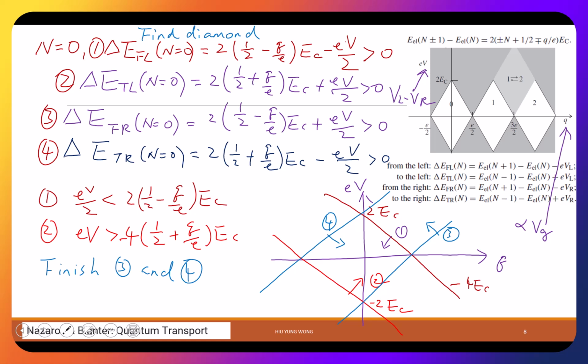Now, go back to, if you took 274, right? We use a single electron transistor to sense a charge. When you have a charge, it changes the potential of the quantum dot. Then you will be able to transport the electron, and then you can measure a current. But if you don't have charge, you put it in this regime, and then you won't be able to transport. So once you have a charge next to your single electron transistor, the whole thing shifts because you have a big capacitive coupling. Then you will be able to transport.